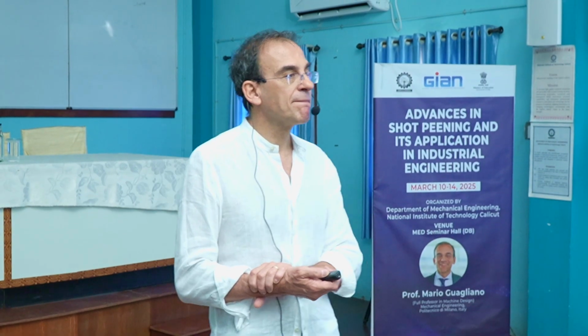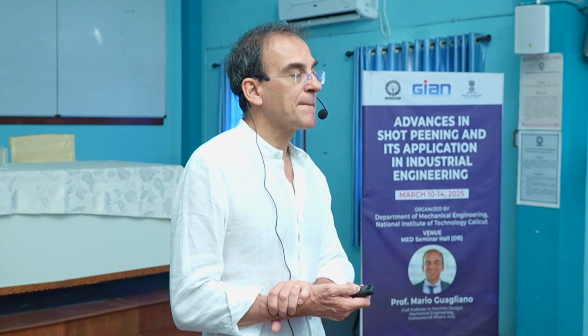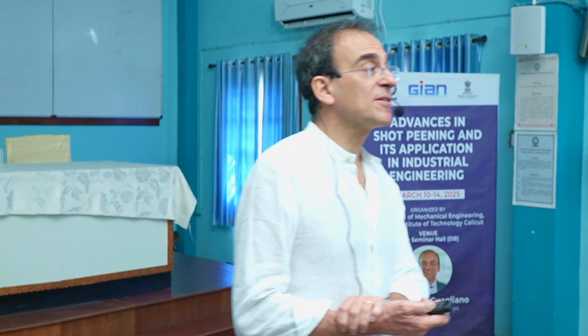Sir, even in this CSP or conventional shot peening, don't you think there is a gradient effect? Because at the top surface you have high compressive residual stresses, and as we move into the depth of the workpiece, slowly it is turning out to be tensile. So is there not a gradient effect in CSP as well? Because from high compressive residual stress on the top surface, as we move to the depth, the compressive stresses turn out to be tensile. So there is a gradient effect in CSP as well, right, sir?